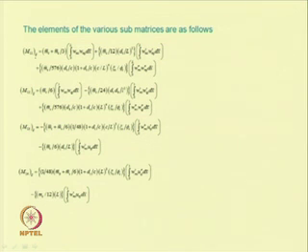So, this M11 ij can be written as (m_t bar plus m_c bar by 3) integration 0 to L W_mi into W_mj dx bar, plus m_c bar by 12 (d_t by L) square integration 0 to L W'_mi into W'_mj dx. So, this dash is differentiation with respect to x.